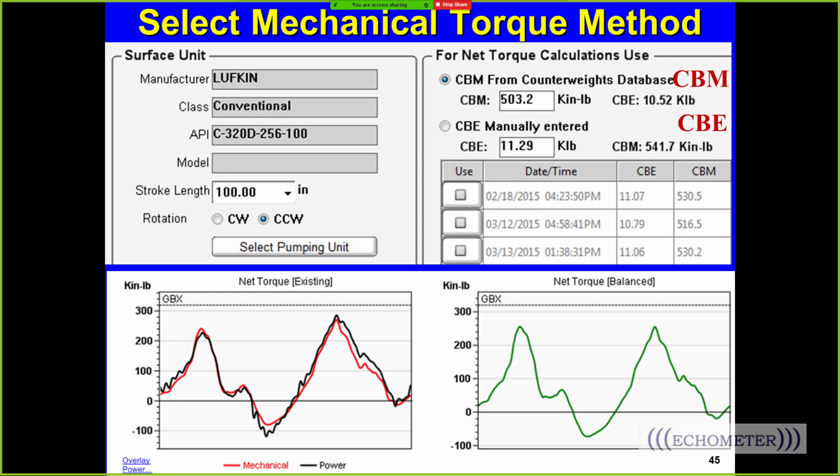The other question is again for which method is more accurate, and you already covered that. And another question is how effective is the CBE method when performed on a well with a leaky pump? Oh, it's really hard to do the CBE method on a leaky pump because you can't balance the rod loading. The weight of rods and fluid is constant, but the pump load is changing really fast. So you can't release the brake and catch it and determine the balance. It's almost impossible, so you probably can't do it because it leaks too fast.